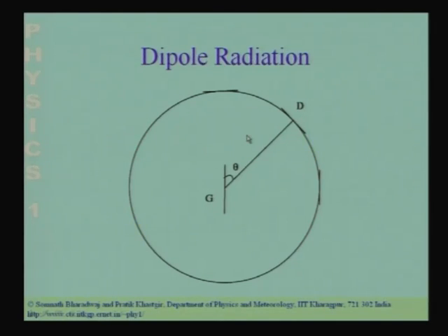So, this is a common situation where I wish to transmit some kind of an electromagnetic radiation. I have a dipole oscillator and I have connected a voltage source. The voltage source is the signal which I wish to transmit. So, the voltage source is driving my electrons up and down these two metal rods, and this gives rise to electric fields elsewhere. Now, I wish to study the electric field pattern.